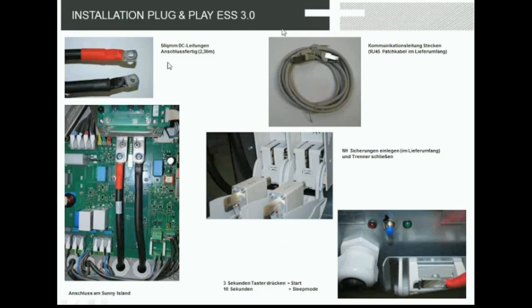Ring lugs, 50 millimeter square, M8, plus and minus. I told you, red is plus, black is minus. That will be directly connected to the SMA Sunny Island, this is a picture of it. You have a patch cable for the communication. You have to have NH1 fuses.